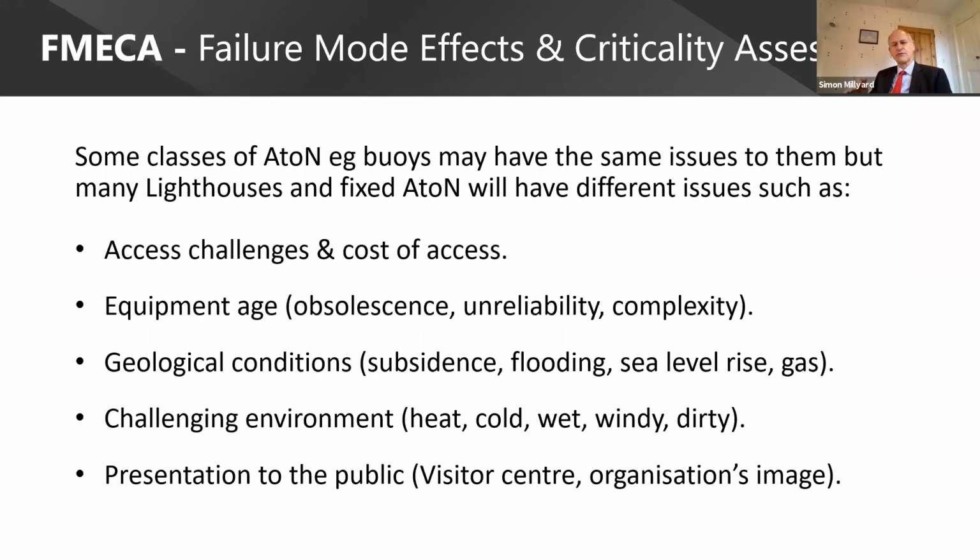And you would go through that for every system that you have, or every leg of that system within your AtoN navigation. And from that, you could then decide where you wanted to place your attention on the design, the installation, the maintenance strategy that you would use. And of course, many people do this subconsciously anyway in a range of risk assessments in daily life. But the FMECA approach, you would document it and record it so that it supported your decisions as to why you were doing this on your lighthouse every year or every visit.